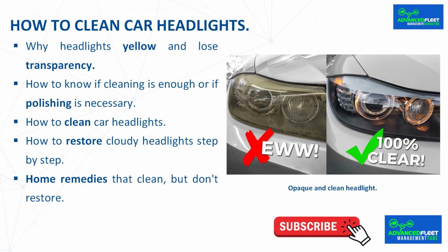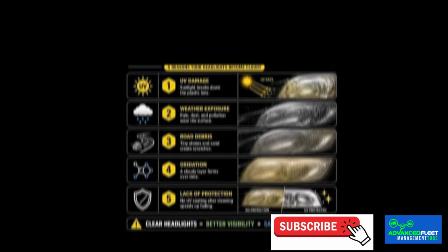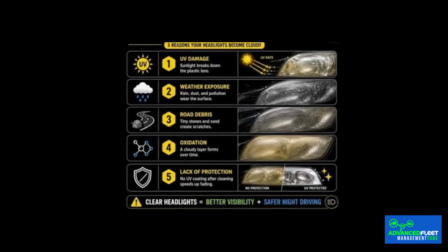Most headlights incorporate a polycarbonate lens, which is factory protected against ultraviolet rays. Various factors, such as sun exposure, harsh washing, and road debris, can compromise its integrity. When headlights show signs of deterioration, a change in the finish is observed, acquiring a yellowish and opaque tone, which affects the headlight's ability to project light properly.